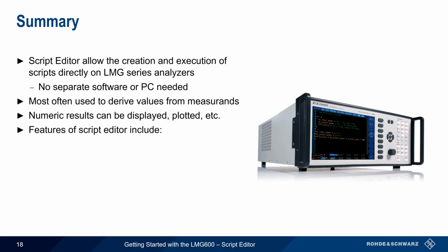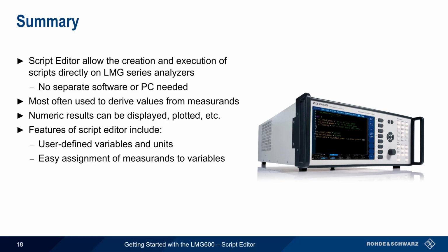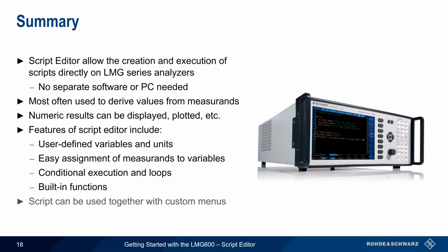Script Editor also has a number of useful features, including user-defined variables and units, and easy assignment of measurands to variables. Conditional if-then statements and for-style loops are also supported, along with a variety of built-in functions. And lastly, scripts can also be used together with so-called custom menus to further enhance and customize the calculation and display of measurement results. This is covered in a separate presentation.